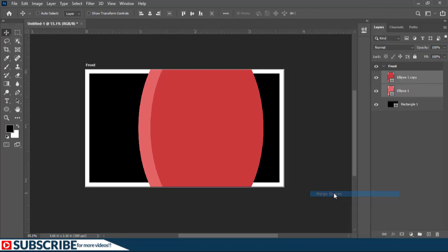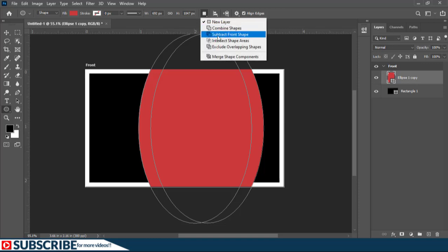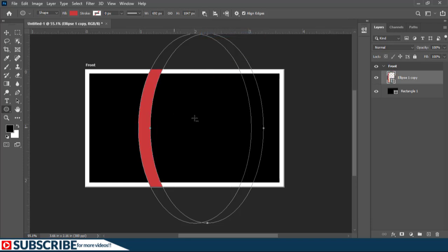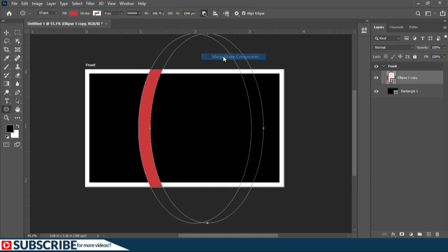Now I'm going to shift click on this ellipse one to select these two layers, right click and then choose merge shapes. Now with my ellipse tool, I'll click on this button on the options bar and choose subtract from shape. As you can see, I'm left with just this piece here. This piece is going to be used as a reference. Now I'll click again here and choose merge shape components to make it one piece.